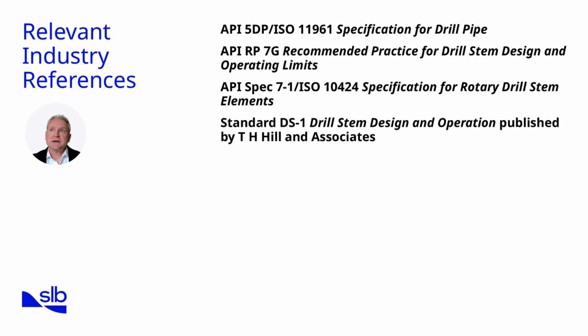Drill string design is underpinned by industry standards that provide both baseline requirements and best practices. The American Petroleum Institute, or API, sets minimum specifications for drill pipe, collars, and connections, including dimensional tolerances, steel grades, and mechanical properties. These standards ensure uniformity and compatibility across the global industry.